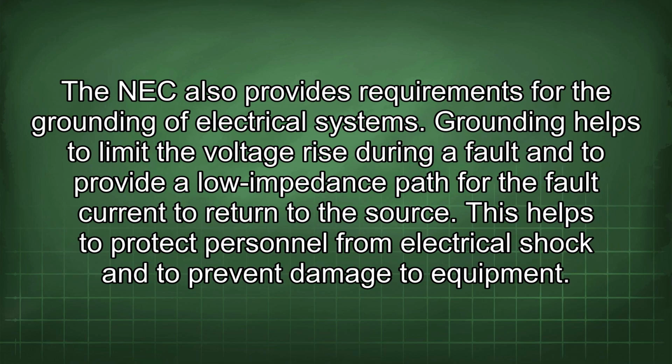The NEC also provides requirements for the grounding of electrical systems. Grounding helps to limit the voltage rise during a fault and to provide a lower impedance path for the fault current to return to the source. This helps to protect personnel from electrical shock and to prevent damage to equipment.